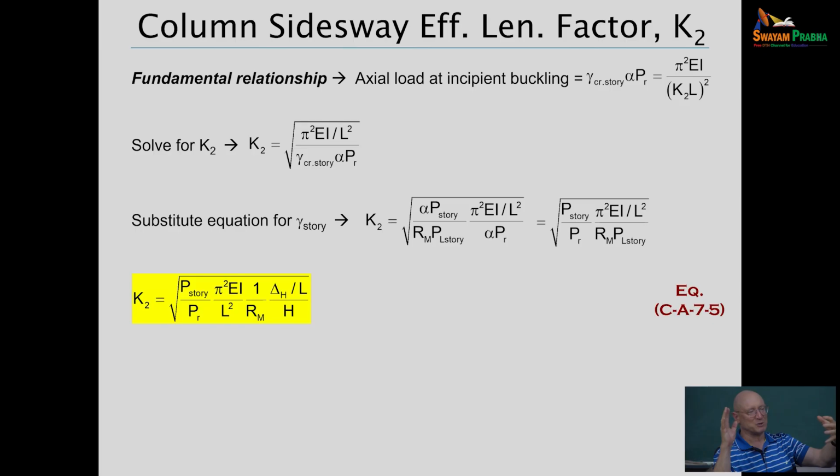So the rest of the sway frame is essentially bracing that member. And so it's a sway frame, but you're actually getting an effective length factor less than 1 for that very light member. That's confusing to a lot of folks because we're used to using tools where we say, oh, it's a side sway, K is always greater than 1. No, it's not.